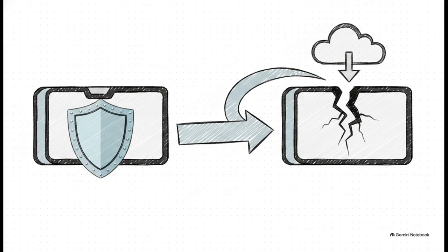If any of those checks fail, like from one of those torn writes we just talked about, the system's boot pointer automatically redirects right back to Bank A. It instantly rolls back to the safe version, totally preventing the vehicle from getting bricked.